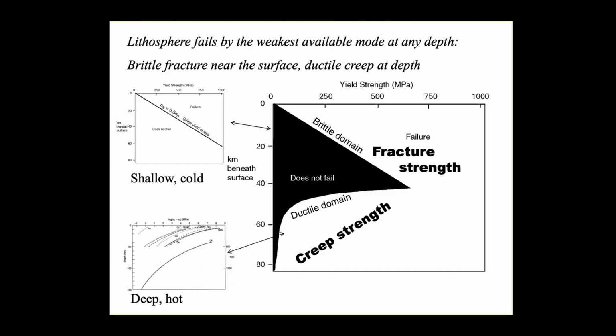But at temperatures higher than about half the melting temperature, the strength falls away very, very rapidly until there's absolutely no strength at the melting temperature, of course. And that's what was responsible for the failure of the towers. The steel was heated up enough that it lost the structural integrity it had when it was cold. Good point.